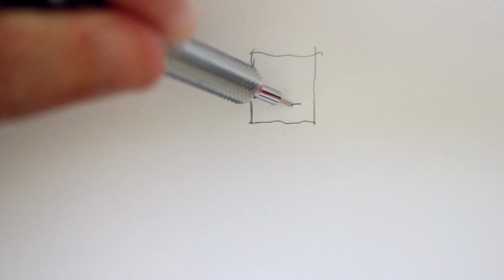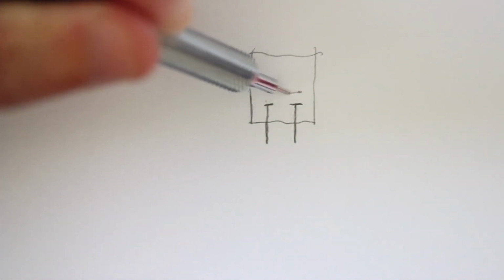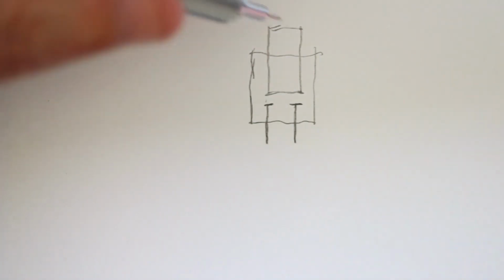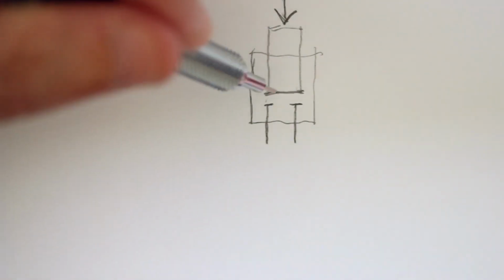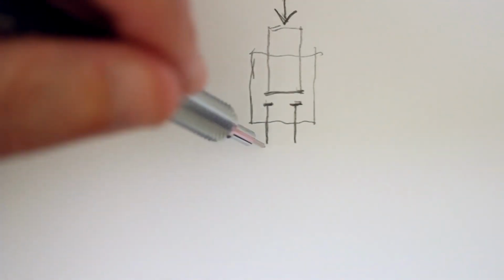Push button switches are mechanical components. Within this push button switch, you have leads that have contacts at the leads. Then you have a plate. This is a very simplistic diagram. When you push down on the push button, this conductive plate creates a contact with the two plates that connect to the leads, creating a complete circuit.